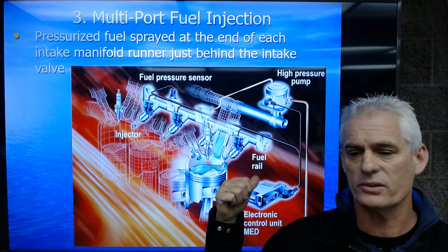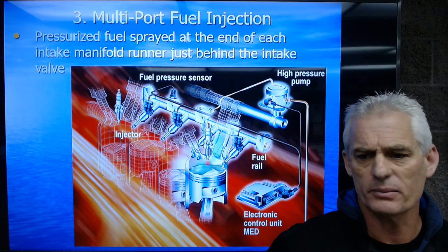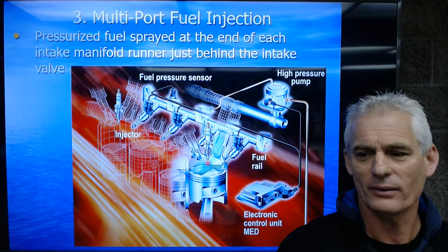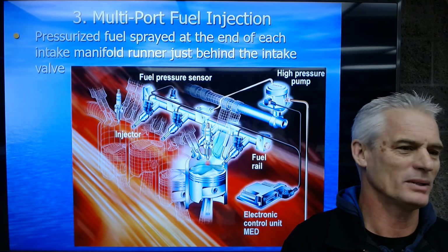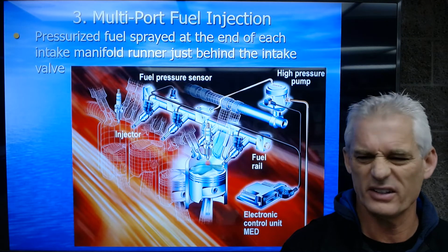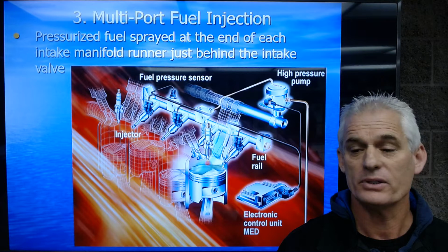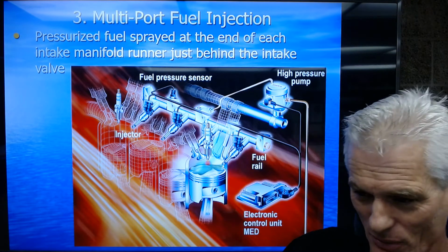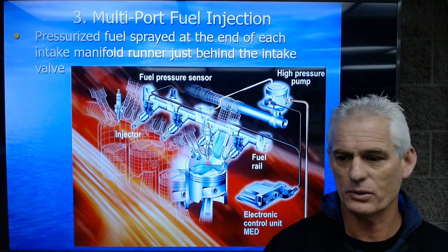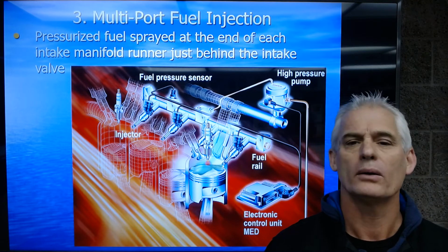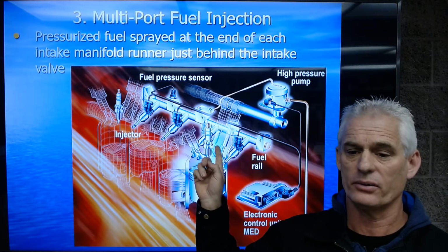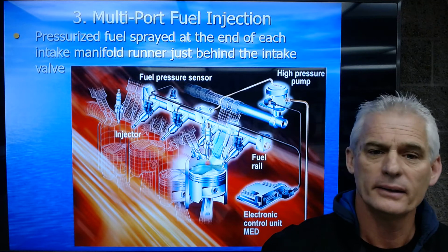We'd like to use just direct injection, but there's some problems that come with it. So everybody used indirect injection from, let's say, the late 80s up until 2005-ish, depending on the car company. And then we started seeing direct injection, and then we started seeing problems with direct injection. And so 2015 to 2020, now 2021, we are seeing cars with both direct injectors and indirect injection, where it's pointing at the back of the intake valve.